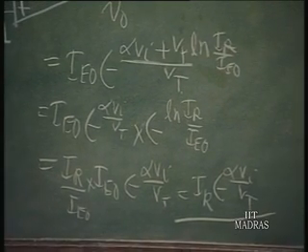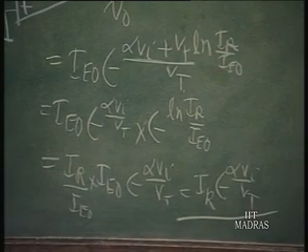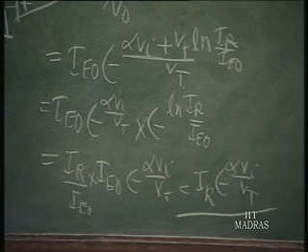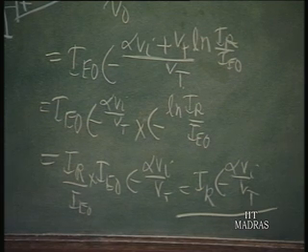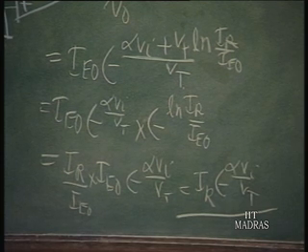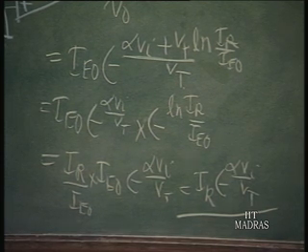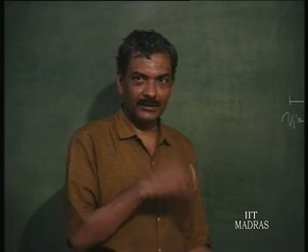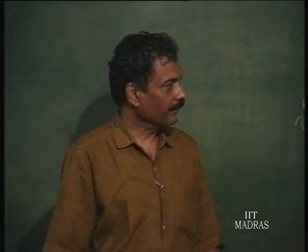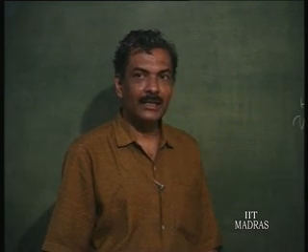So, this is a data expander with temperature compensation, and this is what should be used as a decoder ultimately. Once you code it in log form and then do the processing, you can do the decoding, so that whatever is occurring in the log form comes out of log form, gets expanded and comes in the normal form. So, this is what is normally done in the so-called anti-log amplifier.